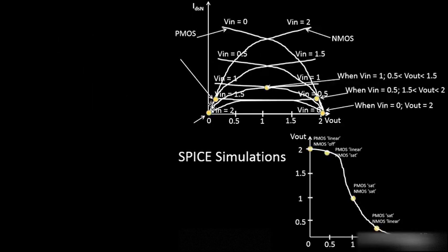Now this circuit has to be fed with some waveforms to identify the output characteristics. For example, you take this PMOS transistor and this NMOS transistor, and their characteristics will look something like this. These curves, which I will be talking about shortly, are the characteristic curves of NMOS. They describe NMOS transistors, and an inverted form of these curves describes the PMOS transistor. Then you simulate this using SPICE, and you get a waveform something like this. This waveform will decide the delay of this particular cell.